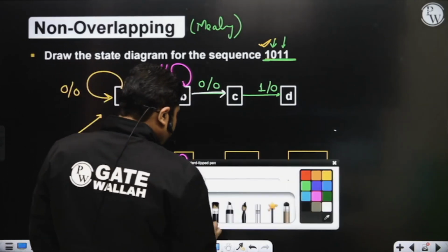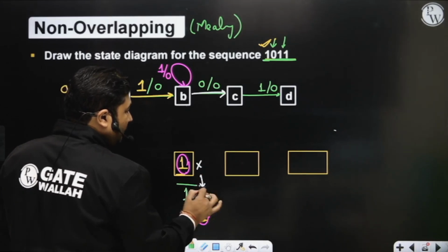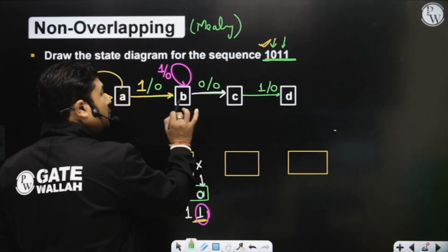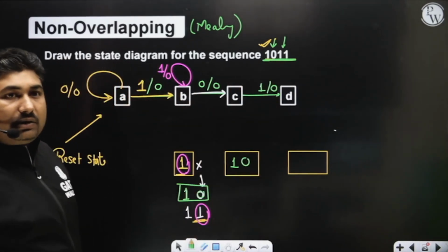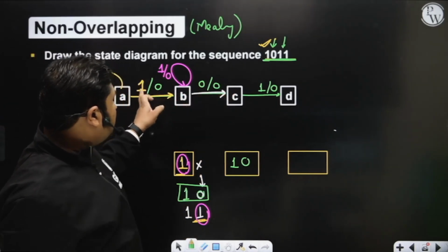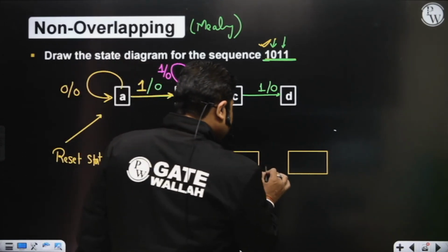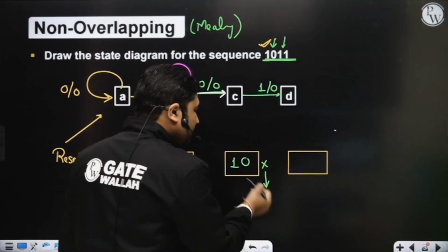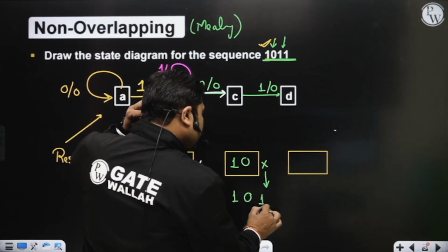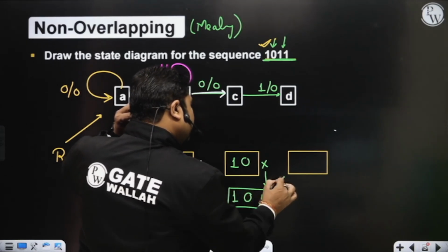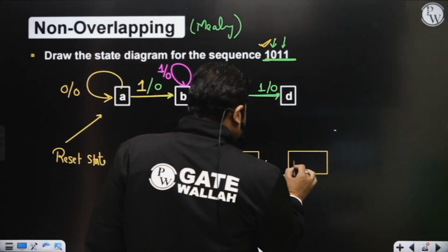Great, sir. Further, if x equals 0, then 2 bits in a sequence got detected. So you have reached the 2-bit state. Now you are on state C. With x equals 0, you have reached state C. On state C, again, there are two possibilities for the input x. X may be 0, may be 1. In case x equals 1, then the required sequence will be detected. Yes, sir. You can move to the next state.